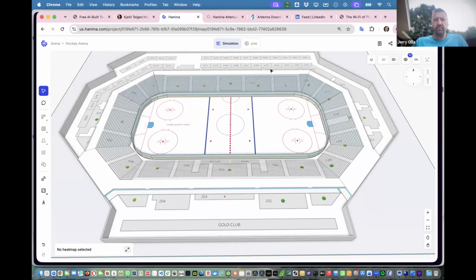Yeah, so you could even take a floor plan like this and essentially duplicate the floor plan and then crop to whatever areas that you want to include in there, and then cut out the other areas to say, okay, this is a hole in the floor for this section, and then just keep the section that you want.